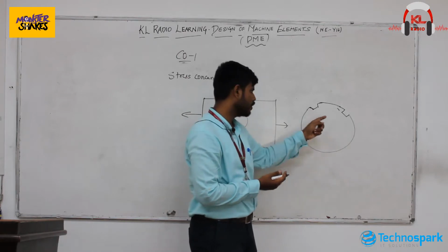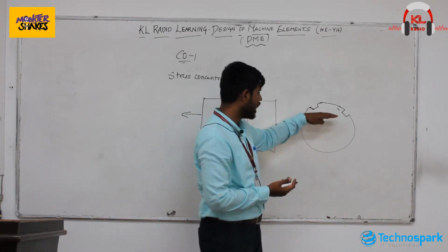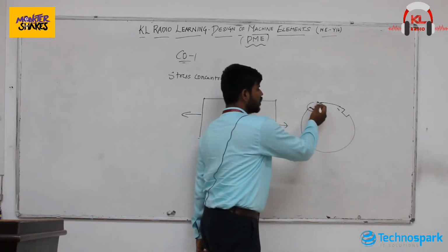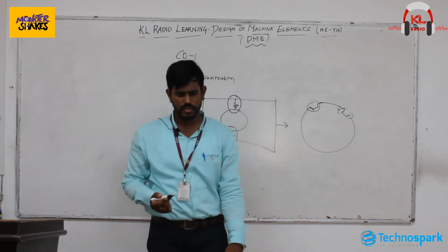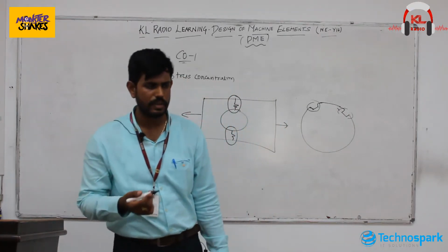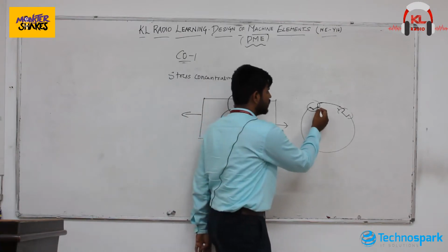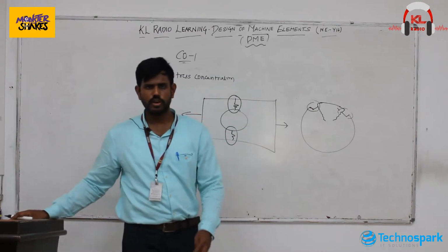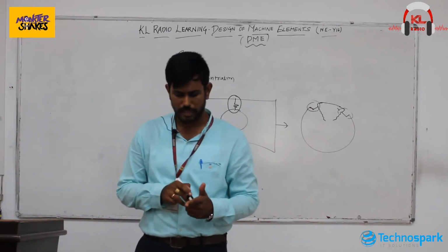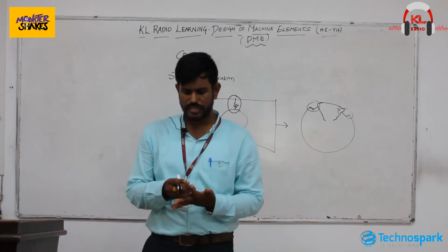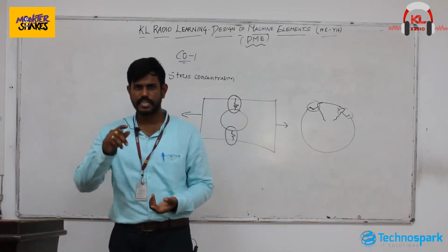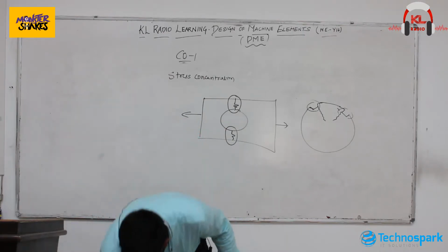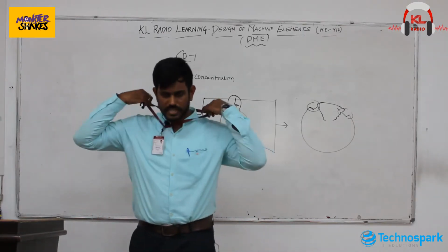When it is rotating, the stress acting at the outer parts will be more because there is a discontinuity in the cross section, which gives rise to severe stress concentration, and you can observe cracks developing in this direction. Bolts are the best example for this, because for bolts you can see the threaded section, which has a change in the cross section, which results in heavy stress concentration.